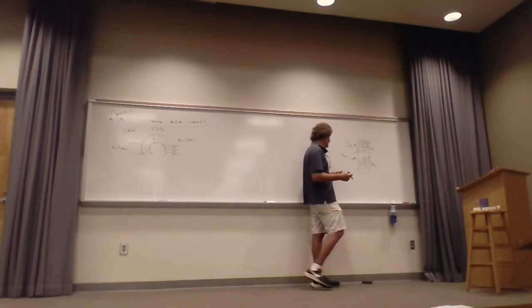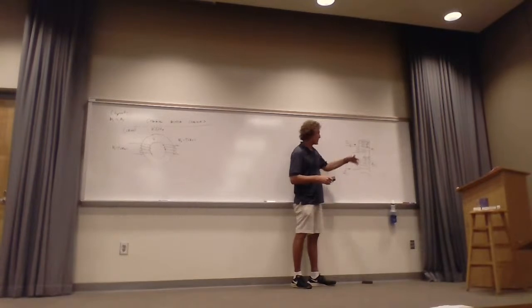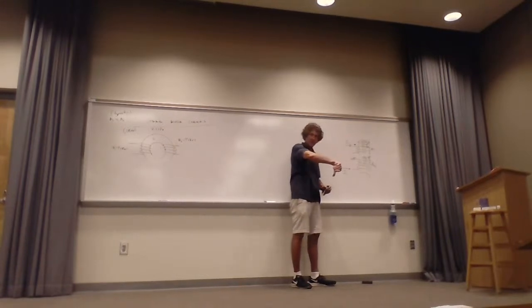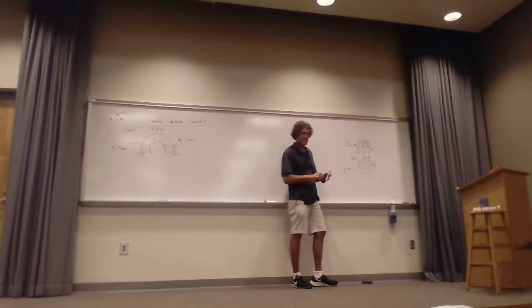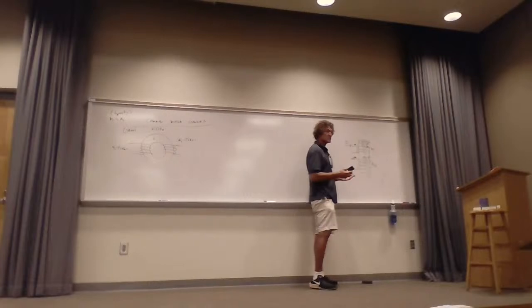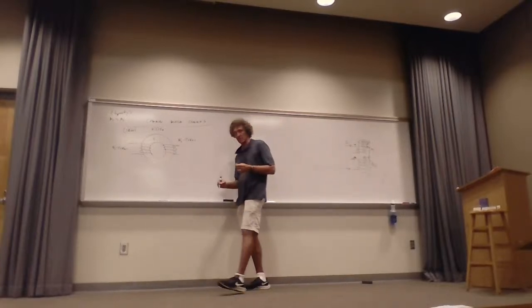If, perchance, suppose I said, well, I'm going to put the current in here, and the fluxes wouldn't align, would they? Then the flux in the bottom one is going to be going down and into. And whenever you get opposing fluxes, you dot the opposite terminal. That's how you get the dot convention. And that's the simplest way possible. Now, it's important to remember that. I'll get to the equations that govern this.